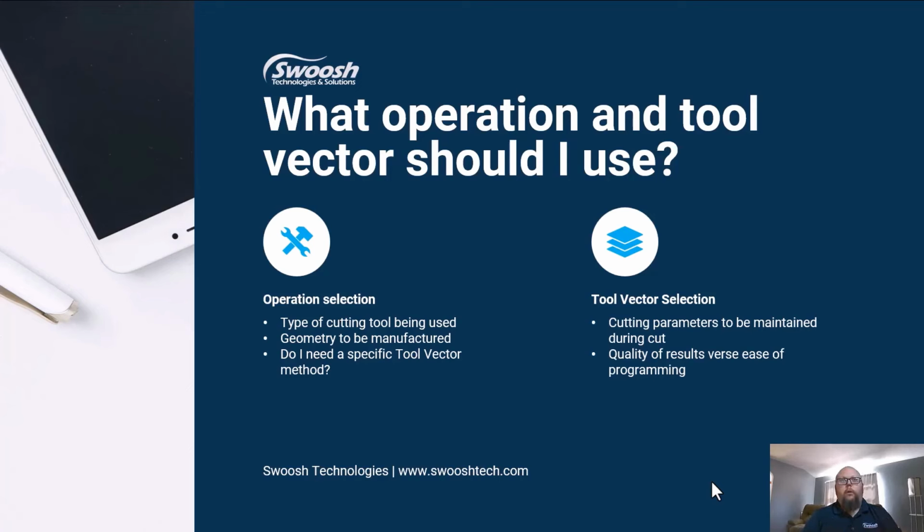So how do I decide what I want to do? Well, then I can start thinking about tool vector options. Again, as you get to know which tool vectors are available in given operations, you'll be able to start thinking a little bit more carefully about what you need. The other thing that comes into play is quality of the results versus effort spent programming. If we're working on a part that needs to have the best finish possible, I need to get near a mirror finish, or I need to really control my tool axis to a high degree.